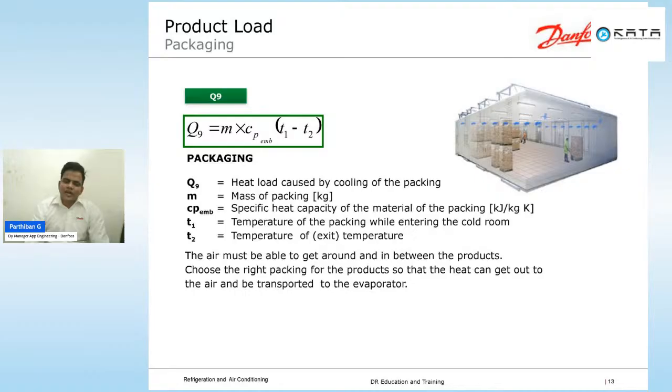So till now we have calculated the product load. We will split this product load into three parts: first is heat load before freezing, heat load during freezing, and heat load after freezing. How to calculate all three we have discussed.